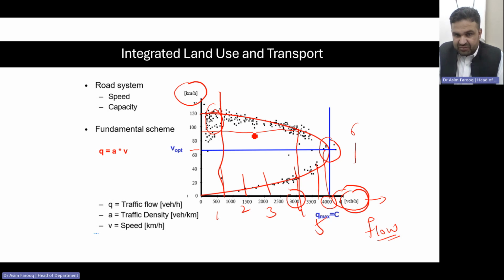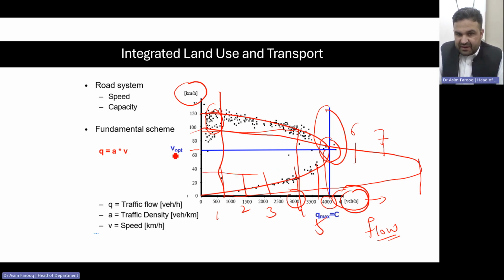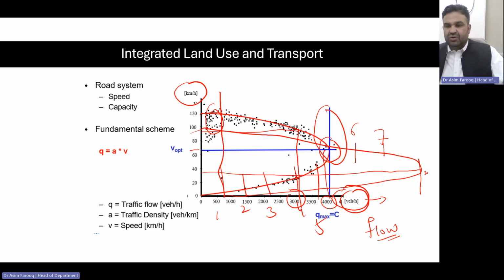Should we build 6 lanes? Should we build 7 lanes? And you can see the pattern that the trend is actually going down. With the passage of time, there will be a time when we come up with a new pattern as here. So maybe after building 9 lanes, we might end up somewhere here, which is 30 kilometers per hour. So in a smart way, or thinking in a sustainable way, it is not necessary to build more roads, but we need to build through sustainable development, and also adopt the transit oriented development concept, and that should be connected with pedestrian facilities and the built environment.